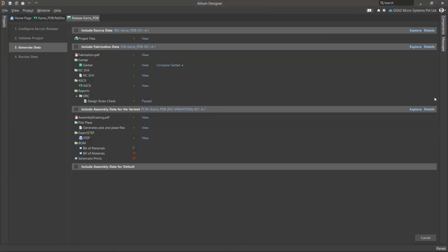This process will help the designer not to make any kind of mistakes while getting the Gerber, because if you have any issue in terms of DRC or the footprint comparison and you don't have this kind of process to release the Gerber, if you are releasing the normal way, then the tool will let you generate the Gerber without doing all these checks.